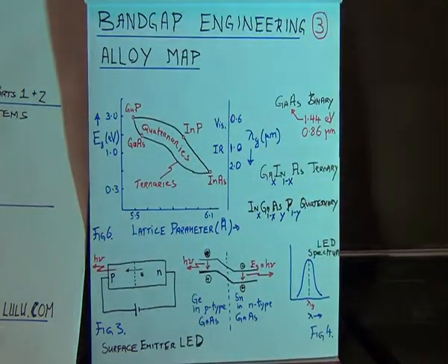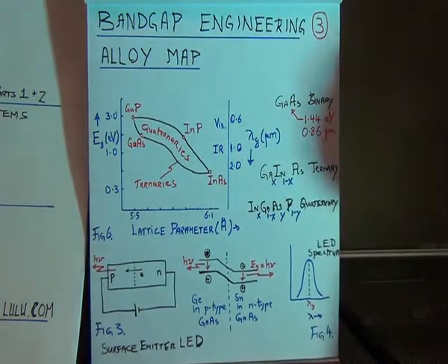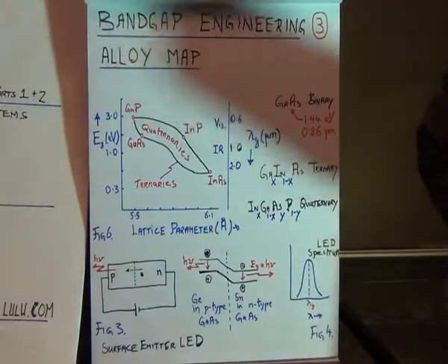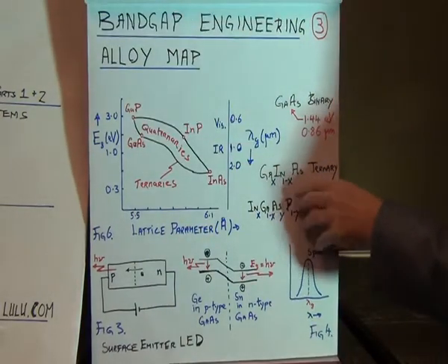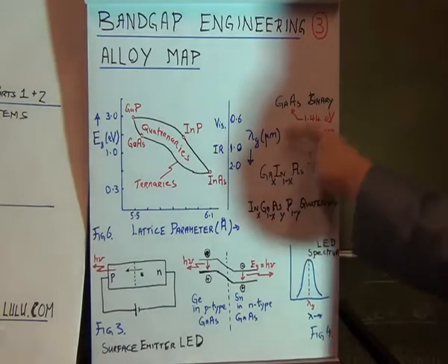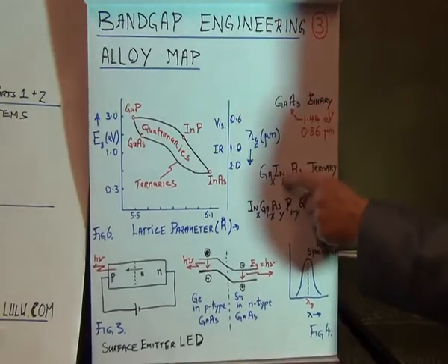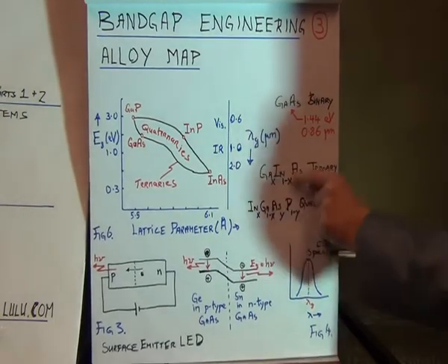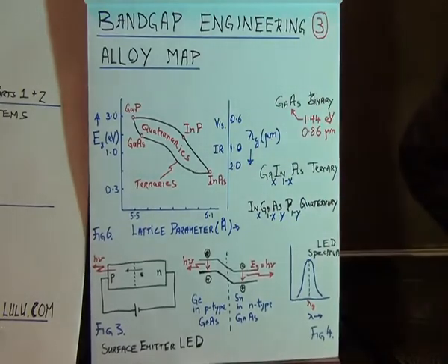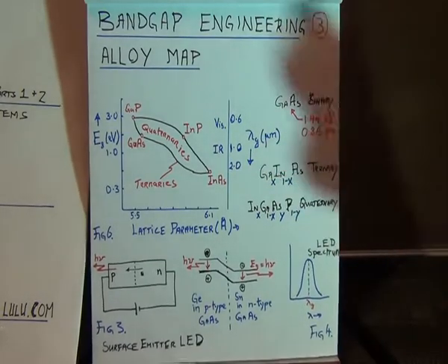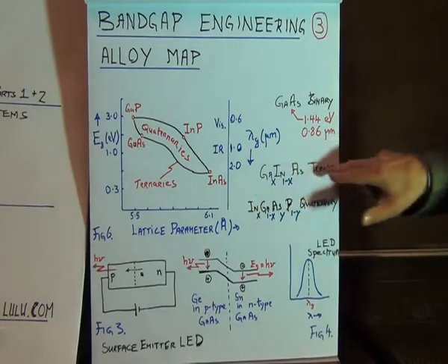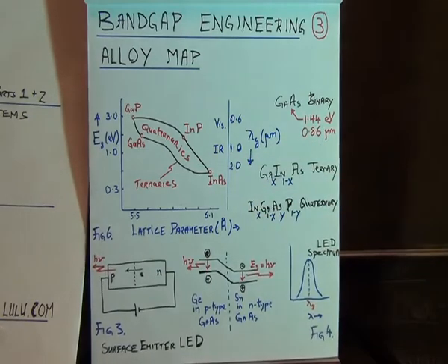Okay? So if you took conventional gallium arsenide that you'd already tried to grow in your vacuum chamber and said, no, I'll reprogram the valves and I will substitute for gallium a molecule of indium. So for every X moles of gallium, I will inject 1 minus X moles of indium, and then 1 mole of arsenic. I let them all react and deposit crystal layers. So I get a ternary compound, which is defined by the mole fraction X.